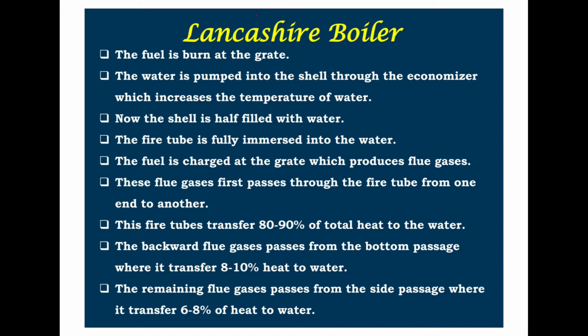In the Lancashire boiler, the fuel is burned at the grate. The grate is nothing but the furnace component, where the grate supports the coal on the top, and the air is allowed through the grate holes. The water is pumped into the shell through the economizer, which increases the temperature of the water.